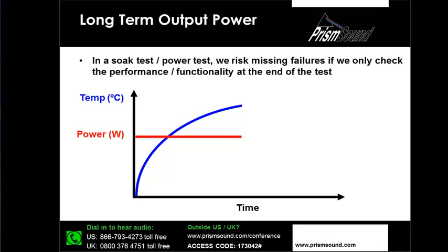That's one scenario, and we'll certainly know if that has happened when we come back at the end of the test. But it may be that this device is sophisticated enough to mute or to lower the gain when the output devices get too hot. So we might see this sort of scenario where the power is reduced or falls to zero for a period of time. Perhaps the amplifier then cools down and recovers.